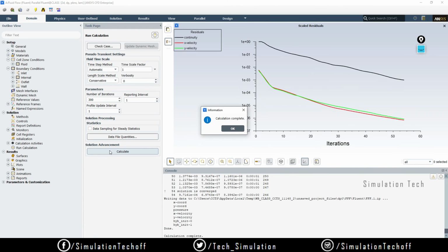Okay, see, now the problem has converged at 57. Like I said before, the convergence greatly depends upon the quality of the mesh. In the previous case, the mesh was in a paved mode, not in a uniform manner. But in this case you will see.